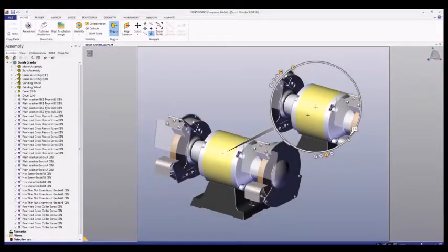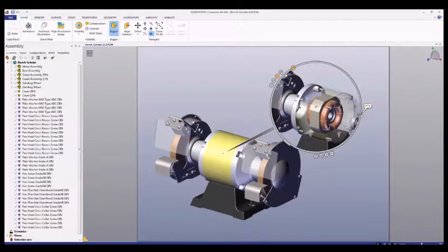The last two tools are used in creating 2D images. Let's say that we want an internal view of the center of our assembly. By creating a 2D image, we can provide that insight while the assembly remains the same. We'll select the X-ray tool and zoom to our desired depth. If we want to save our image, we hover over the Capture 2D Image button.